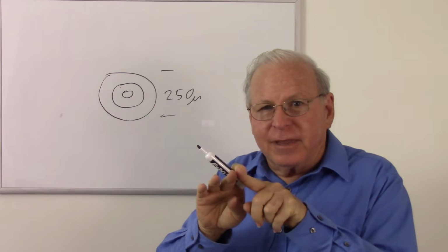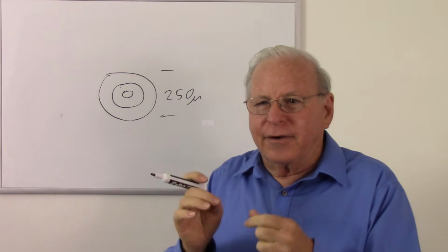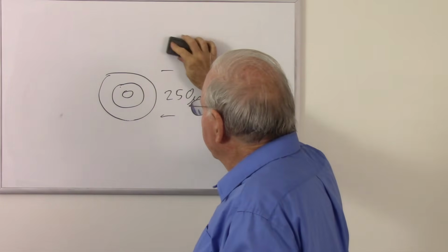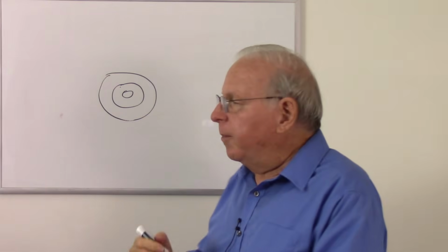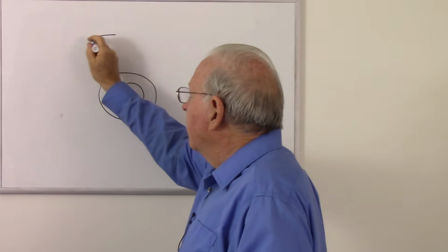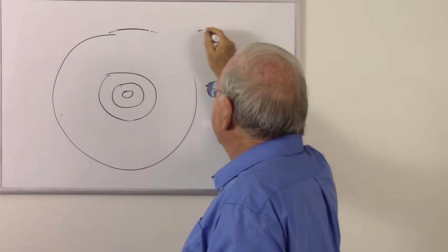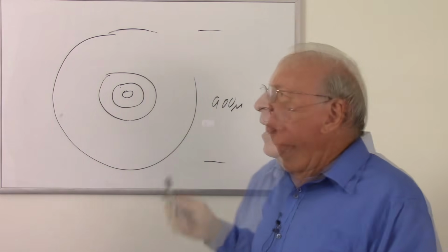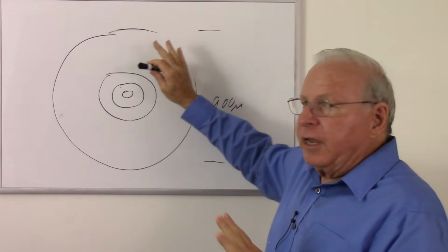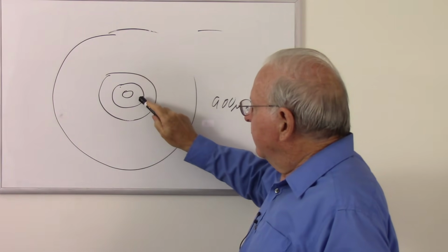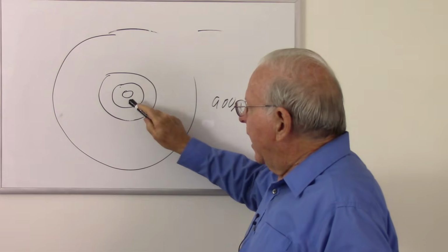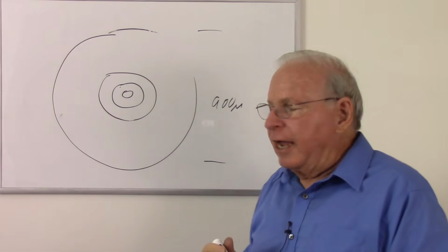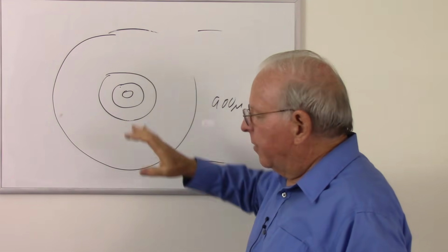Or ribbon fiber, they lay these out on a ribbon and bond them together, and they're typically your 250 micron fibers. But the next type of fiber you may encounter, which is probably most common, is going to have another buffer called the secondary buffer, and it's much bigger, typically 900 microns, made of polyvinyl chloride usually. And so that would be what's called tight buffered cable. So you have the core, the cladding, that's your glass, your acrylic primary buffer, your PVC secondary buffer. That's what's called tight buffered fiber, and they're all bonded together rather tightly.